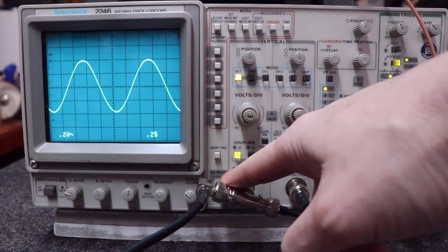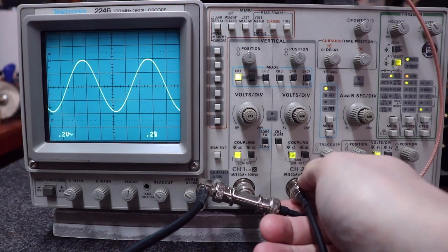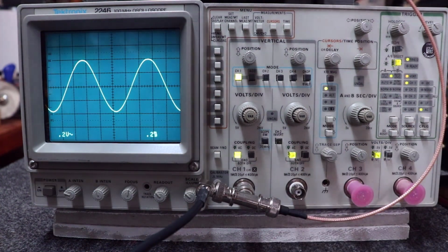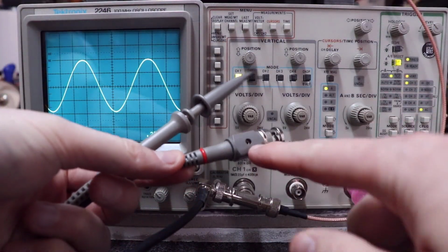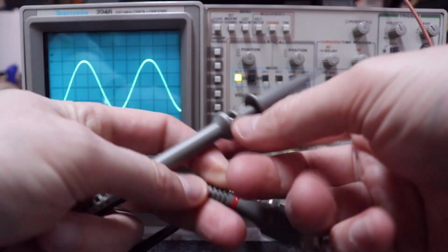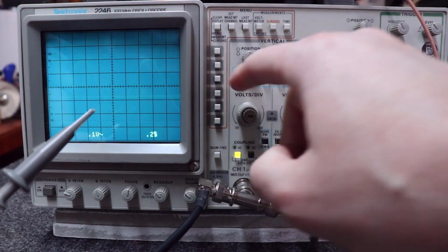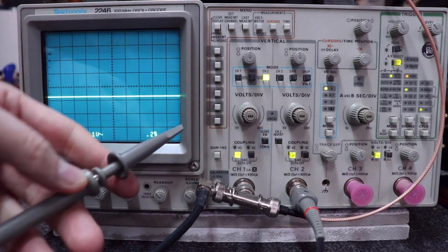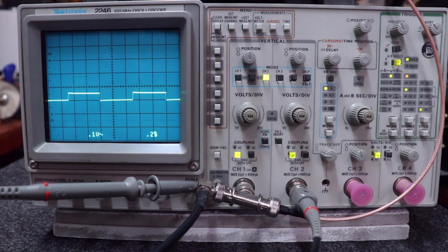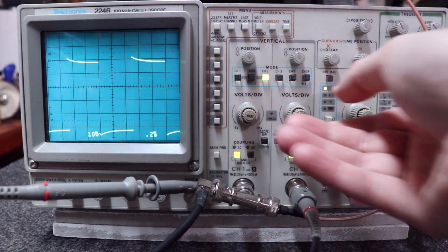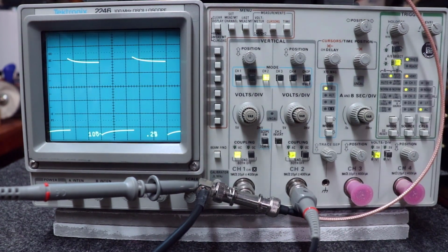Okay, while we're over this way, there's a little box here called Calibrator. And what that is you can use it to calibrate your scope probes. Okay, if you'll notice, your scope probes have a little calibration thing right here. What you do is you plug your oscilloscope in, let's put it on channel 2 and take it off of channel 1. And then you just clip your probe onto this little signal here, and if you'll notice then, it'll tell you that it is a 1 kilohertz signal at 0.5 volts.